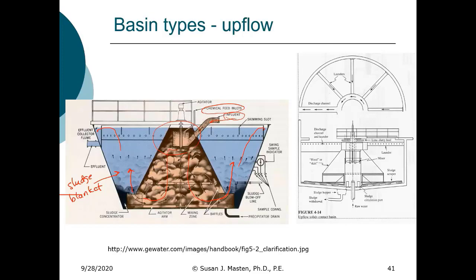So in East Lansing, what they do is they use upflow clarifiers as the primary stage one, and then they add ferric chloride to remove some turbidity because they have water coming in from their sludge drying ponds. So they use ferric chloride, and then they have a second sedimentation system. That's a conventional sedimentation basin, and then the water flows into filtration.